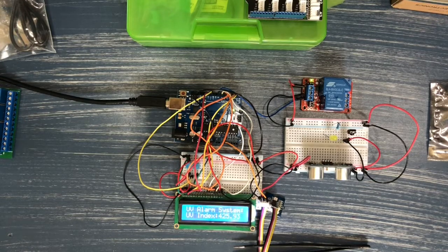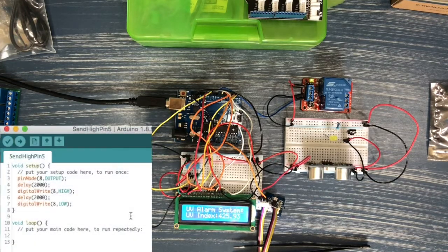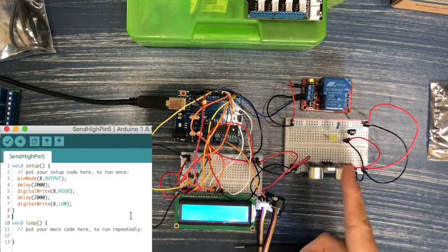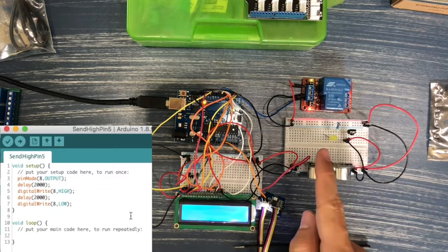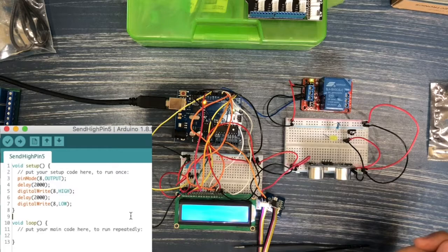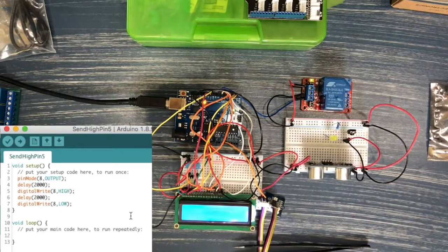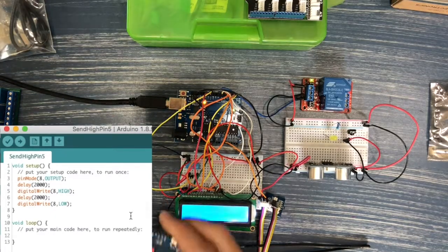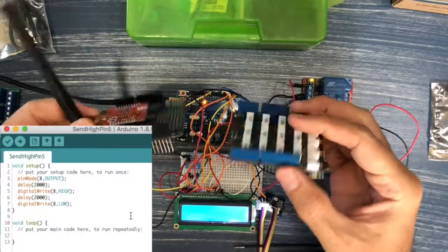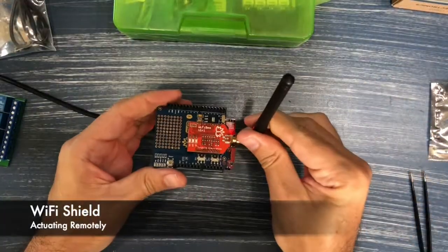Okay, so here is the code for the relay, and as always it is down in the description of the video. I'm uploading the code right now, and you see the LED there, it's on, and then it's off. I only put it in once, which means I put that code in the setup function. Otherwise the relay would just be going on and off continuously, and of course it's not that exciting if it's not connected to anything, but that is basically what the relay does. All we do is we send a digital write high to the pin we are interested in, and then a digital write low.